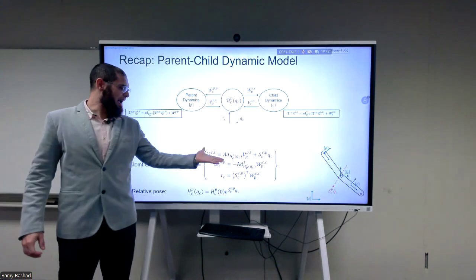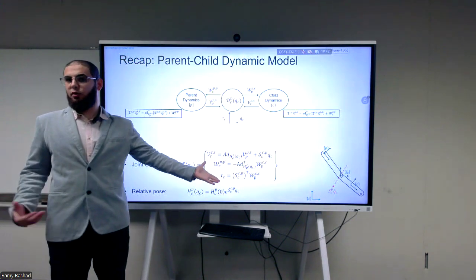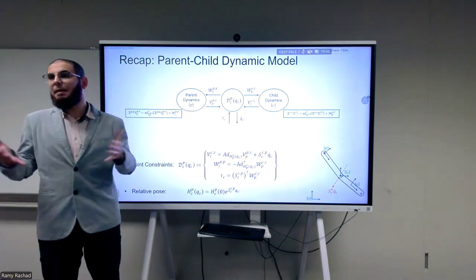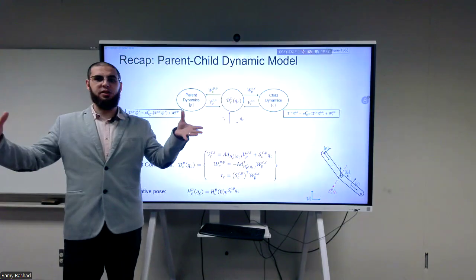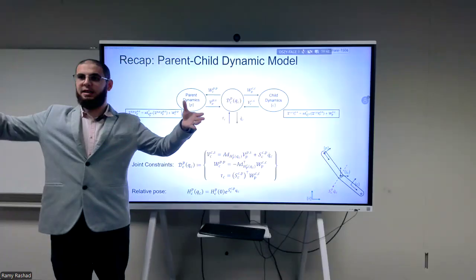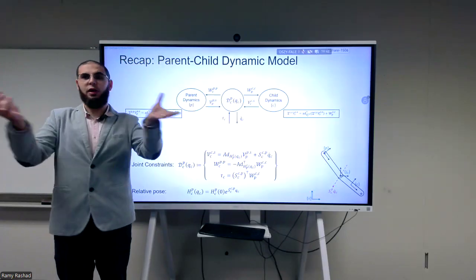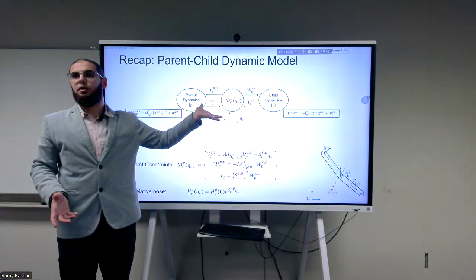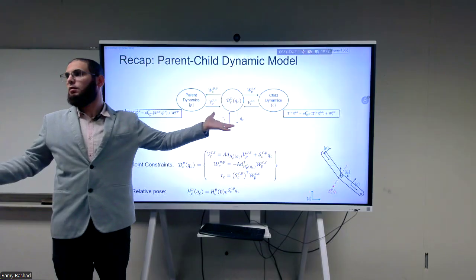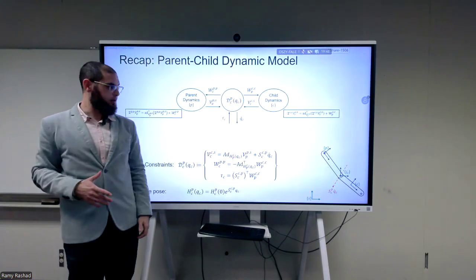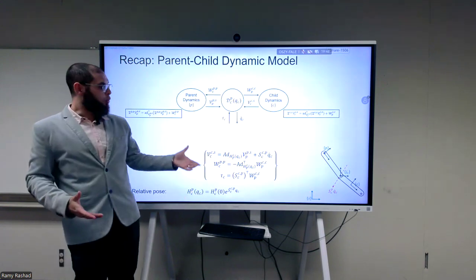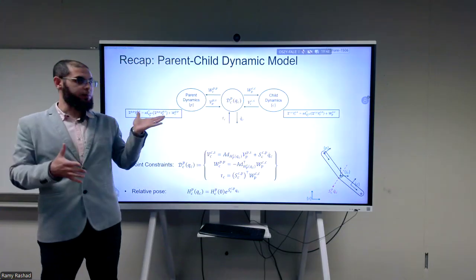Okay, you should be familiar with this by now. And in between, we have a set of 3 equations we derived last time. Do you remember the intuition behind them? They constrain the two equations. They limit the number of degrees of freedom. If you have two rigid bodies that are not connected, then the first rigid body has 6 degrees of freedom. The second rigid body has 6 degrees of freedom. They're free to do whatever they want. If you connect them through a joint, you already lost. You already constrained. If this is a 1 degree of freedom joint, you've already constrained 5 out of the 12 degrees of freedom that both had. So these 3 equations say nothing else than you've constrained these equations.